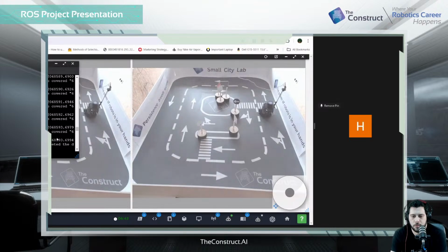What I did was I faced the robot in different directions, checked which array value is the least, and then figured out what the value of the array is in the real robot and the simulation robot. Then I had to change those values and change the value of the right laser and the diagonal laser. That was one of the challenges.